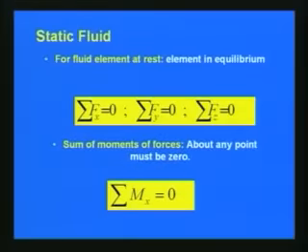So, these fundamental equations, sigma Fx is 0, sigma Fy is 0, sigma Fz is 0, and the sum of moments of forces about any point must be 0. These 4 equations are very much valid in the case of static fluid also. We generally use these equations in solid mechanics, and directly they are applicable in the case of static fluid.